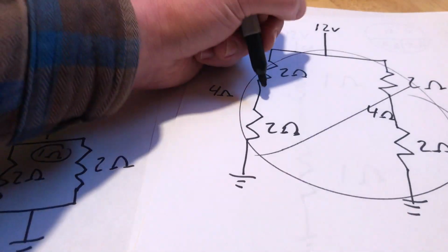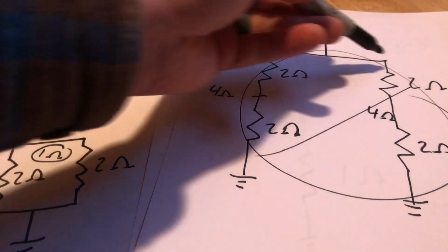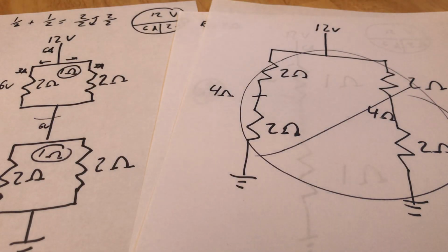If I cut this wire right here, well, then all of a sudden current can flow through that other leg of the circuit. So even though you might be able to reconcile some of the math, the actual physicality of the circuit, the way that it's going to act on a vehicle or on our breadboards or what have you, we won't be able to approach the two the same way as far as diagnostics go. So just be real careful about this stuff.